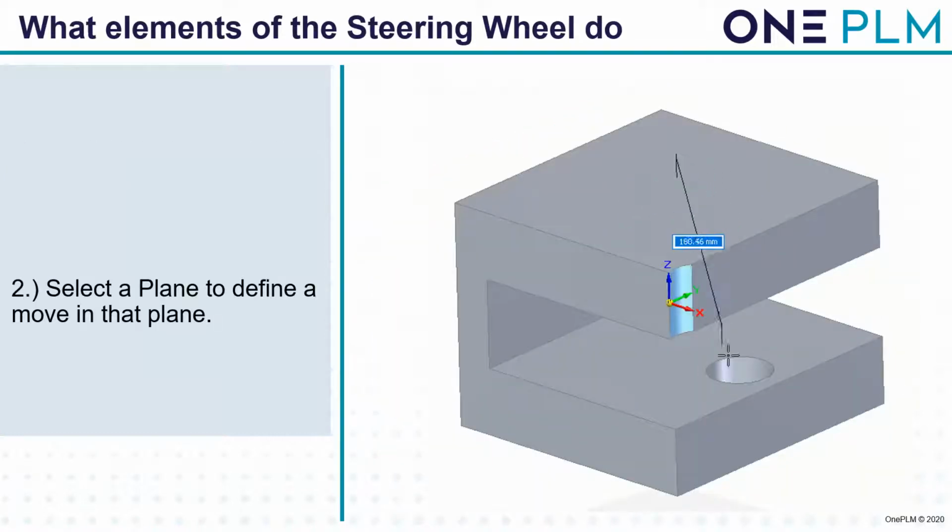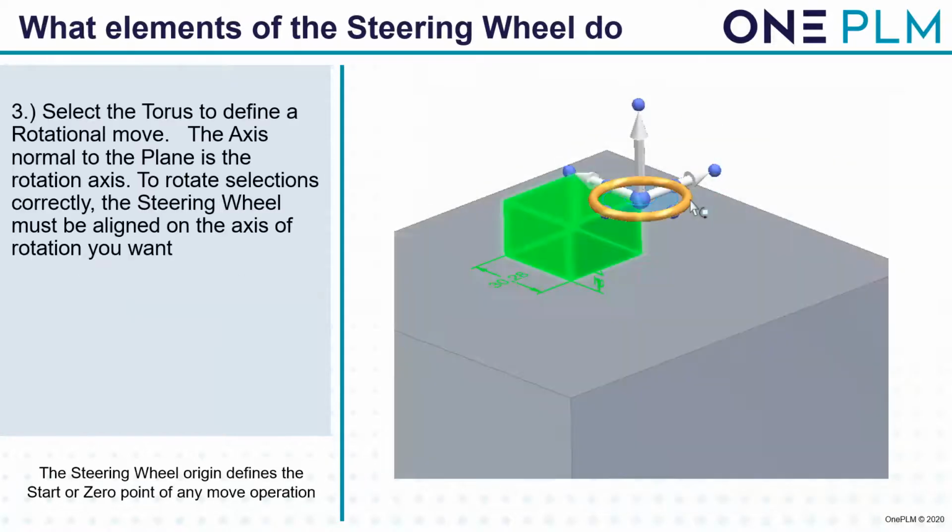So we can also use the tool plane. If we select a feature and then click on the tool plane, which was highlighted orange in there, we can use that to snap. This is very useful if we've got a hole on 2 different parts or in 2 different features on a part, to make sure that we can align those 2 up. So using that, it's just moving it in that plane direction of that tool plane itself.